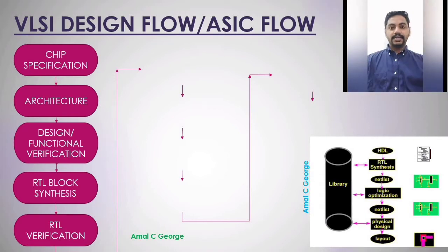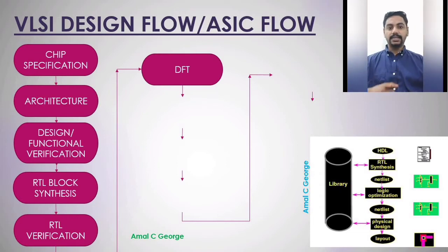The next step in the design is called DFT, Design for Testability. It is meant for providing a method for testing each and every node in the design for structural and other faults. So, the higher the number of nodes which can be tested through the targeted number of patterns, the greater the coverage of the design. For this to be possible, every node in the design has to be controllable and observable. We consider these as two basic principles of DFT which are to be followed in order to have maximum test coverage.